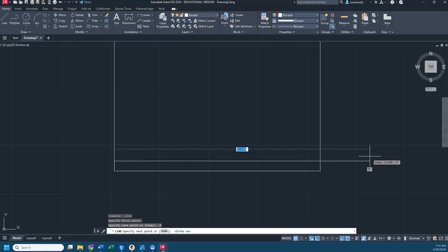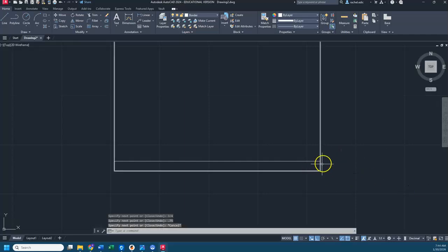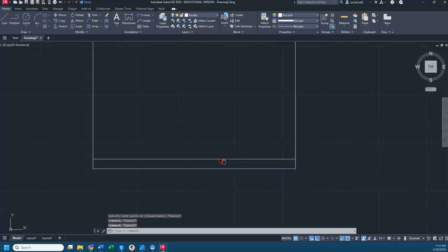And we're going to draw short segments of lines to represent our different sections of our title block. So I'm going to do 0.5 and then press enter. And you can see it drew just that part of the line. So then 3.5, 3, 1, enter, 1, enter, and then 3/4. That still leaves me with a section. If you look, I can see that it's going to be 3/4, but I'm just going to type 0.75, enter, and that's going to close and finish my title block.